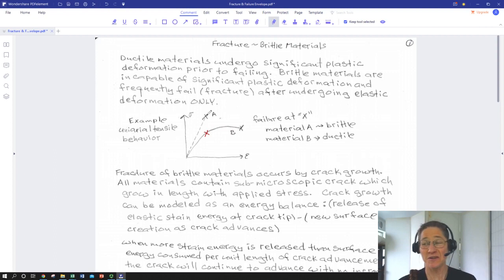Well, there's some materials that aren't going to yield. They're going to break. They're not going to exhibit any kind of yield behavior. But we do know the stress that's associated with fracture if we pull it in uniaxial tension. So the point is we have that data, and in fact we might test this in a different direction.